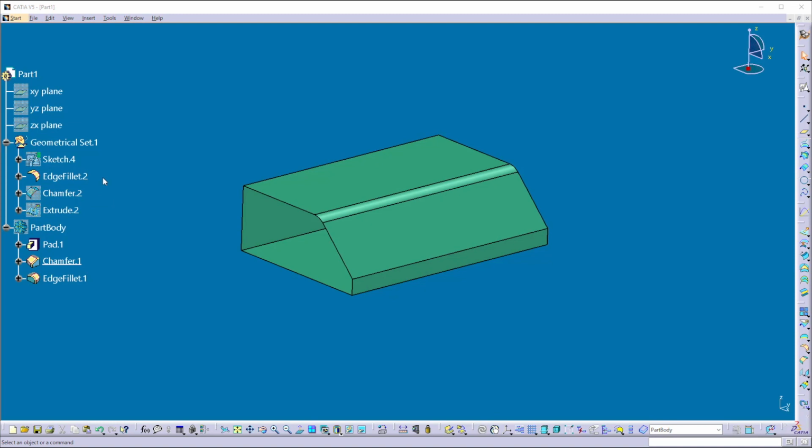Here, you can place any element anywhere in the geometrical set. We don't need to follow the logical creation order. So, geometrical set doesn't follow the order principle. These geometries, the wireframe and the surface geometries, have their individual existence and representations.